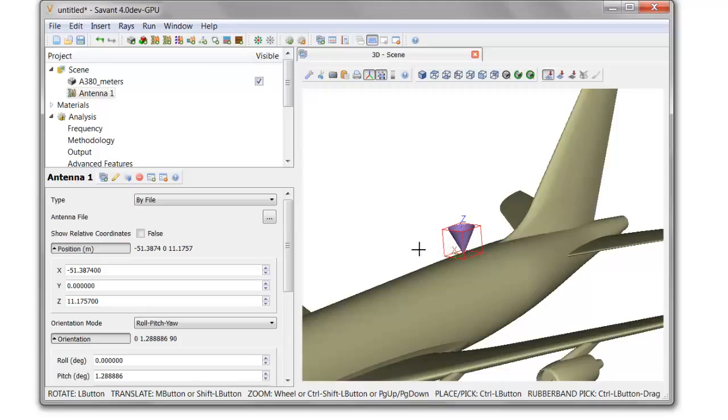That will be a blade antenna. We'll synthesize that in Antenna Magus, bring that into Microwave Studio, simulate it in CST Microwave Studio with a near-field source monitor, and turn that into a hybrid simulation then for an installed antenna model on this A380 in Savant. Let's start the demonstration in Magus.